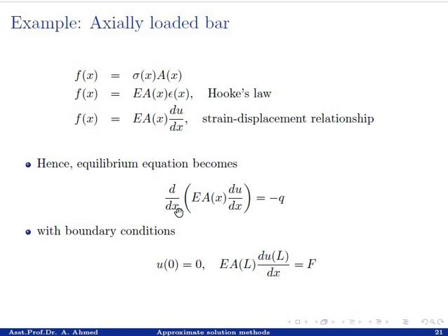You can see that this is the advantage of the continuous formulation: you don't have exact stiffnesses and exact equilibrium equations, but you have differential equations which can take into account complex geometries and nonlinear material behavior as well. This equilibrium equation must be supplemented with some other differential equations, which are the boundary conditions.